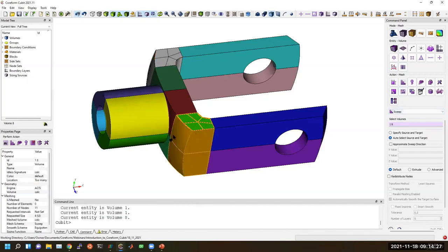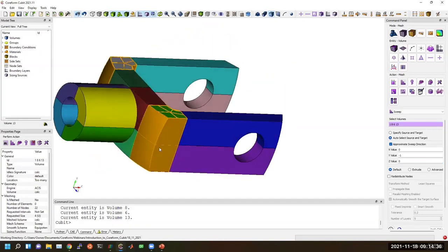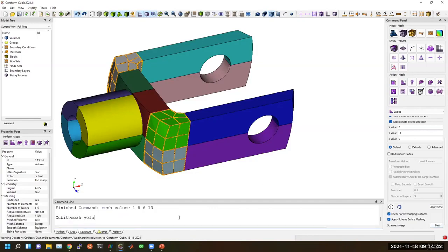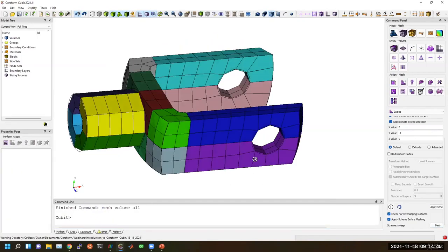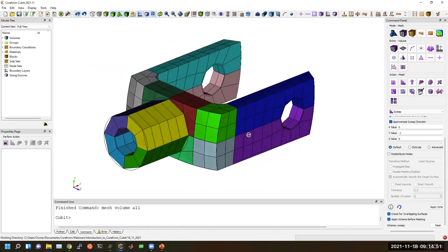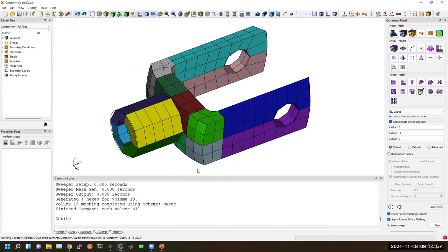Now for these shoulders, we're going to specify a specific sweep direction as opposed to letting Cubit pick one. So we'll tell it we're going to sweep these in a negative Y direction, so sweep from top to bottom. This is now representative of the coarseness of the model that we're going to build our U-Spline on. Right now our U-Splines are supported through command line options. Whenever we do development in Cubit, we always start by developing the Cubit commands, and then we roll out GUI tool buttons for those.